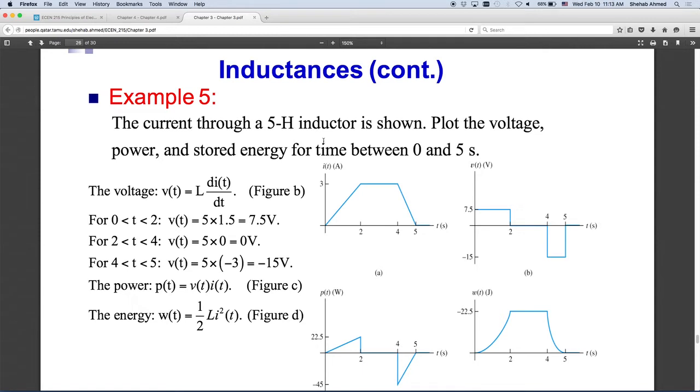With capacitors, we said that there are companies now developing what are called supercapacitors and ultracapacitors, and these are small devices in which you can actually store a decent amount of energy. With inductors, to store a reasonable amount of energy, you have a much bigger frame. So typically people don't use inductors for energy storage as such. They use them more to filter out ripple.